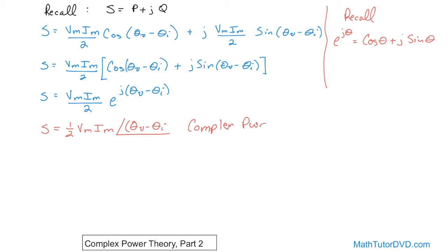Take a minute to absorb what we basically said here. We have this concept called complex power. If you can write it in algebraic form, real plus imaginary part, then you can immediately read the real power and the reactive power off, which is generally what you're always trying to calculate. So the question is, how do you find them? Well, you could go calculate cosines and sines and all of that stuff. Sure you could. You can calculate P with this, and Q with this. That's what we've been doing all along, but we want to show you alternative ways that might be easier.